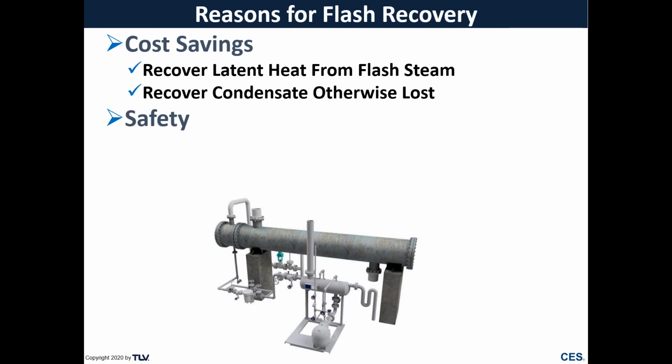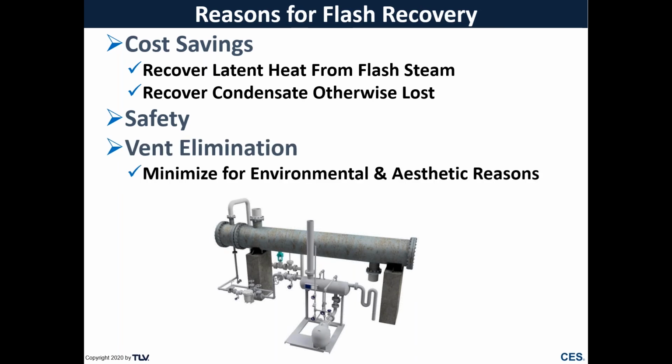Safety: open steam vents can be dangerous. They can lead to decreased visibility due to steam clouds or steam plumes. And in cold environments, this can cause slipping hazards on walkways or stairwells, especially if condensate is carried over in the vent and rains back down, which could also lead to a potential burning hazard. Vent elimination is also good because it can provide a positive environmental impact. Recovering that condensate and eliminating vents creates just a nicer work environment.